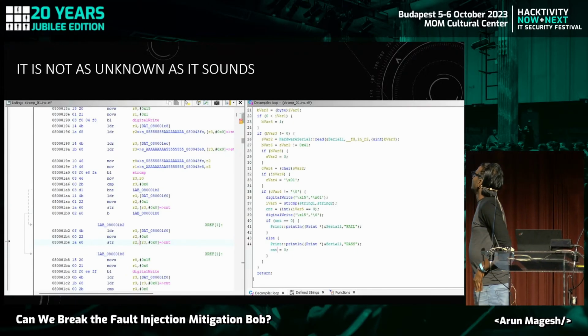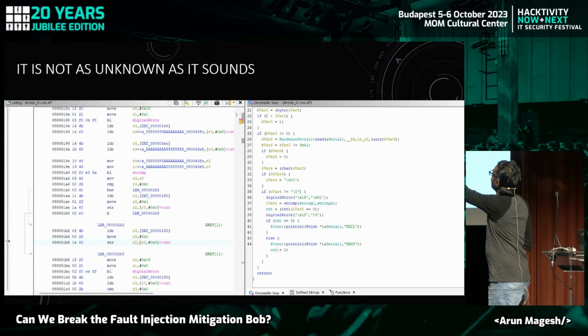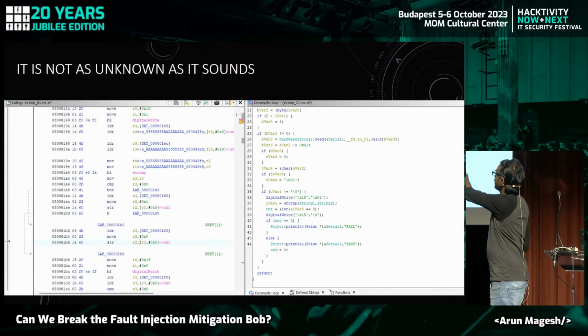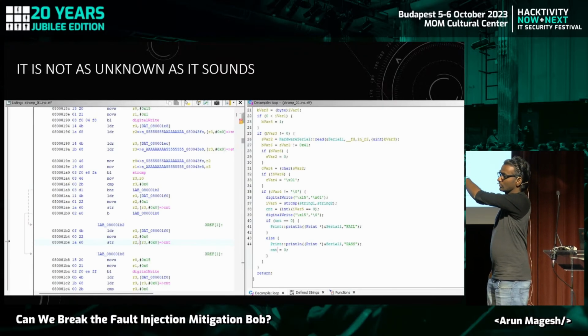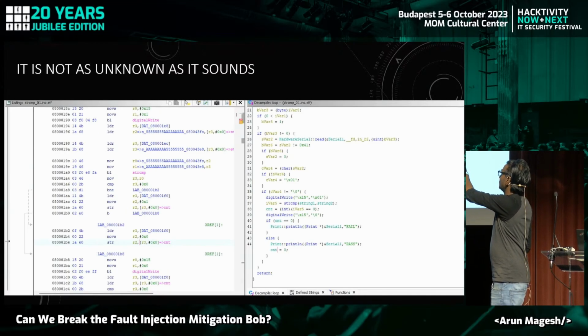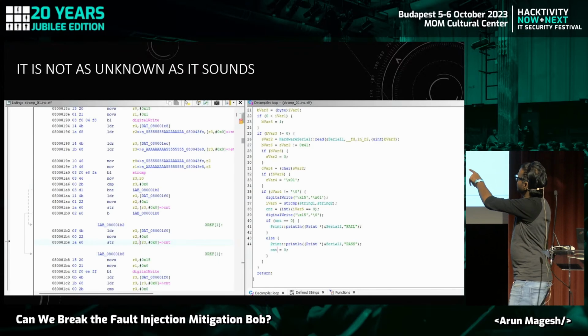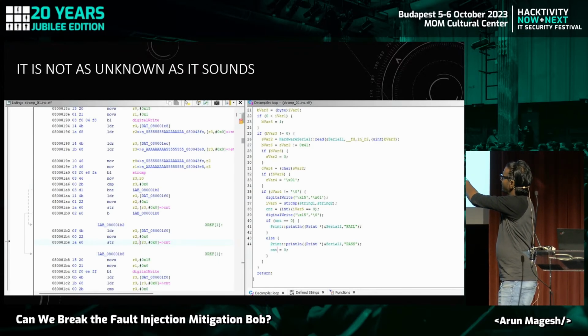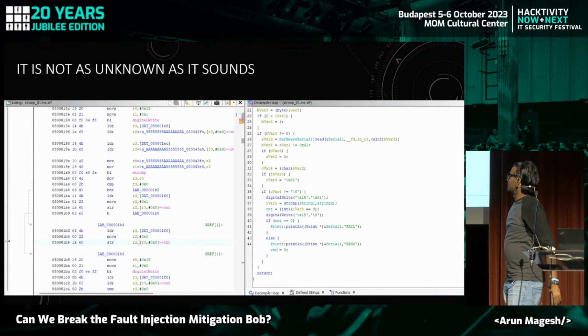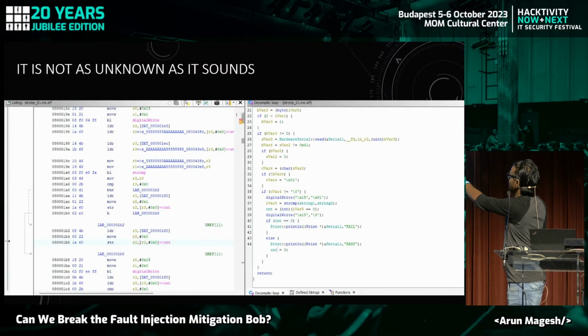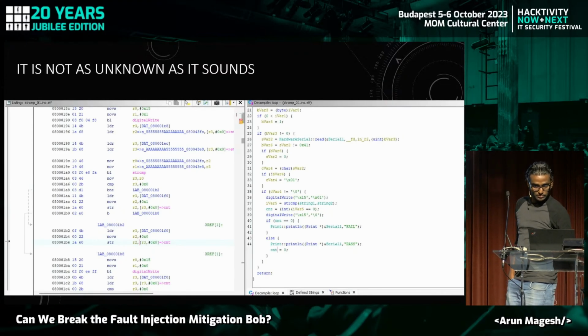Yeah, so first is where all the data is being loaded. For example, you are loading the 2 string values inside a register, and then that is moved to R0 and R1 for a string compare. And then the return value goes to R0, and then goes to R3. Again, we are comparing if it is 0 or not. And then we have branch not equal to. That sets the value to count 0.